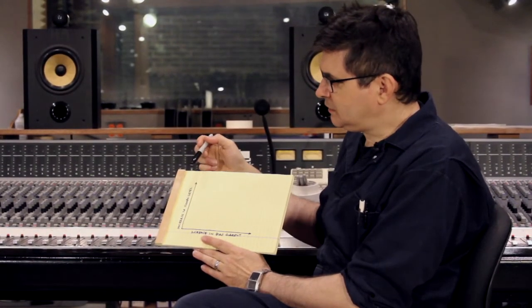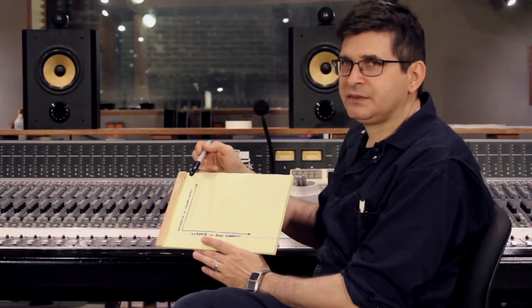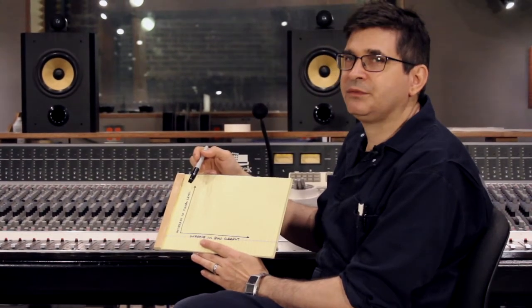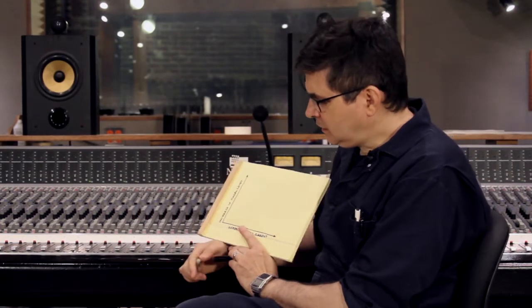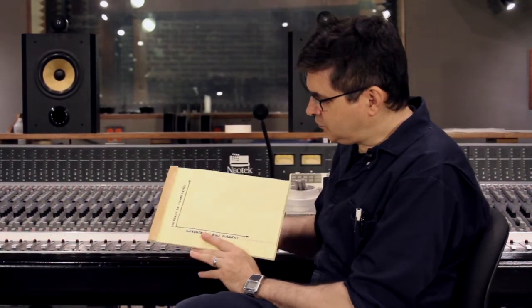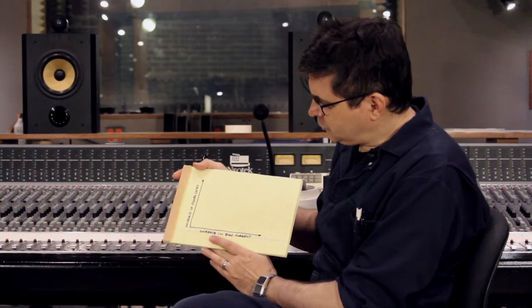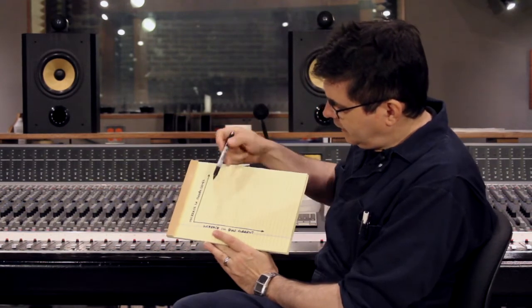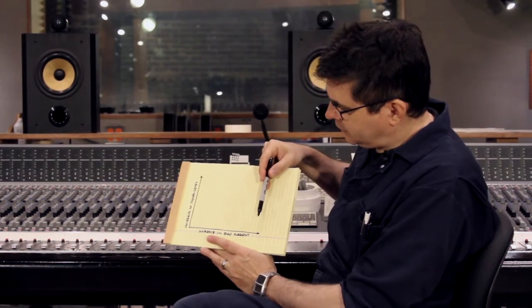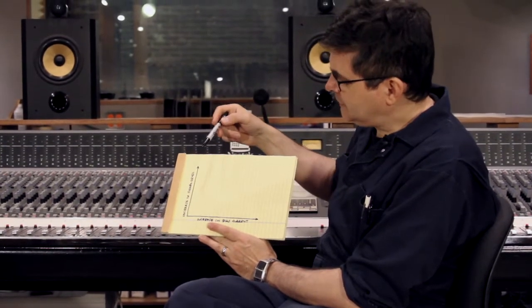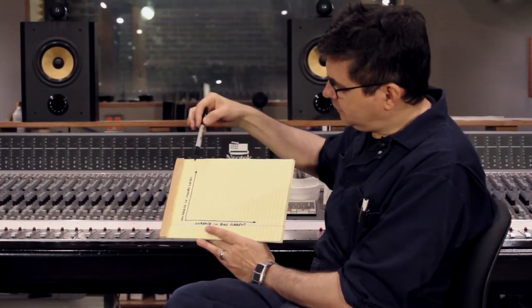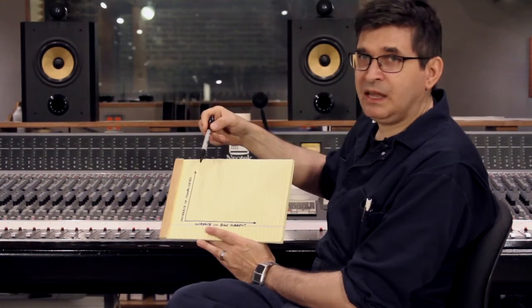As we discussed, without bias, the tape is very difficult to record on. The domains tend to stay put. So if I make a little chart here that shows you, as we increase the bias current, what the behavior of the machine is in different conditions, on the vertical axis would be an increase in level on tape. This is not calibrated in any way, but it's meant to be illustrative.